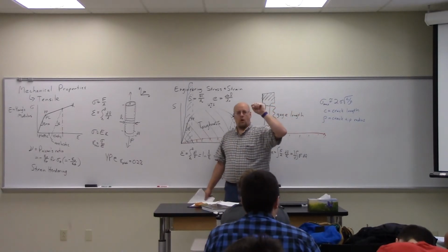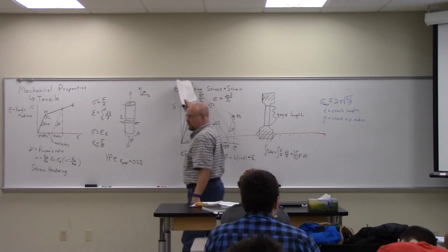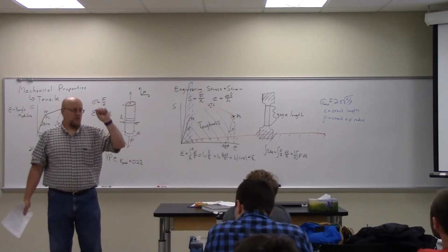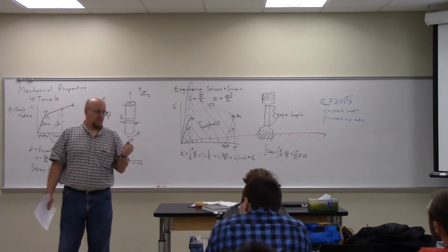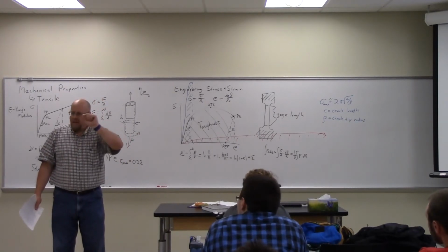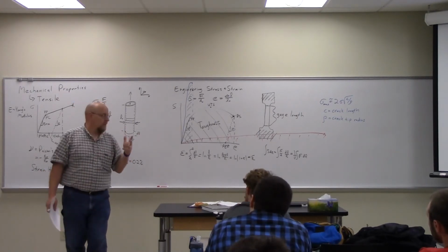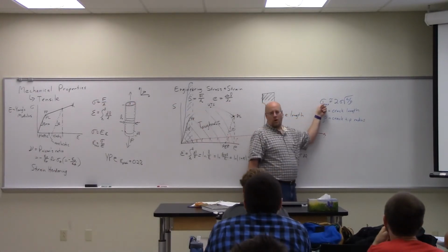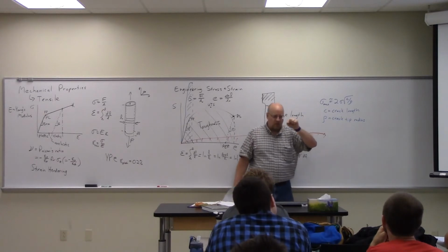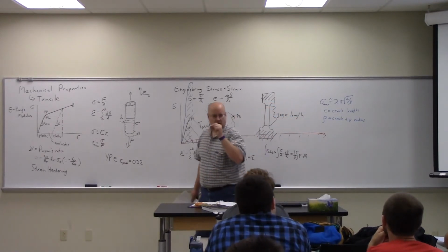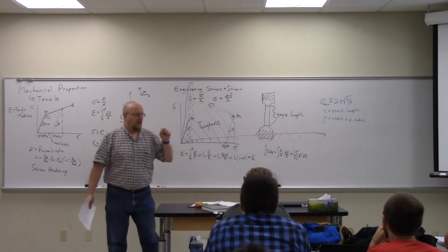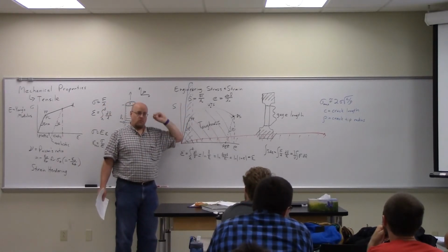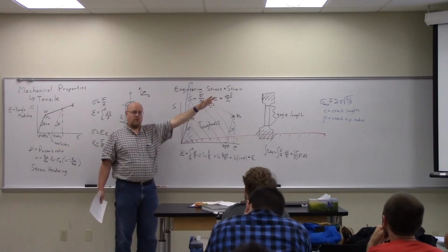So that even though glass takes a tremendous amount of stress to break, if there's a little bit of a defect on the surface of a piece of glass, just a little nick, that little nick will cause a much larger stress to be present at the point where the nick is occurring. And because the glass is brittle, it won't deform much before it'll propagate that crack across.